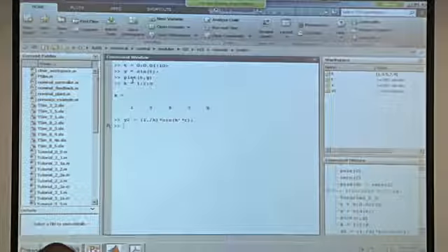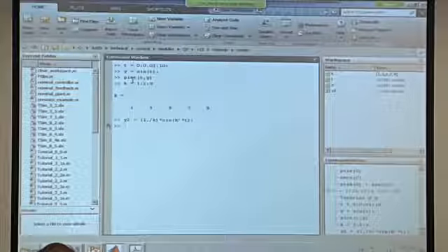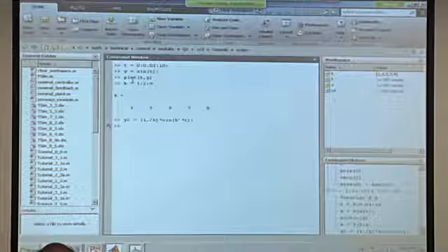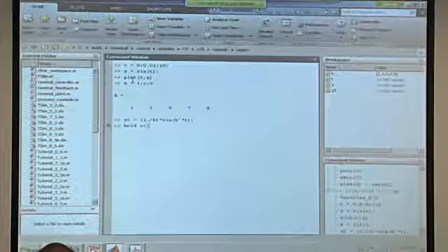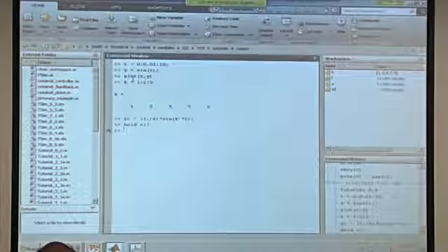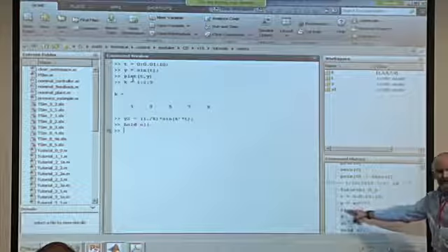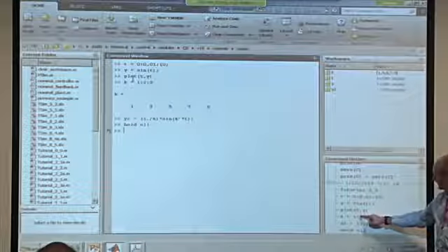Now to show you this, I'm going to plot the results on the same graph that we had previously, and I want to store the previous graph without changing it. So I'm going to write hold all. That tells MATLAB not to get rid of the previous results when I plot this thing. And now what I'd like to do is to reuse this command here. I'm going to plot the new data on top of the old one.